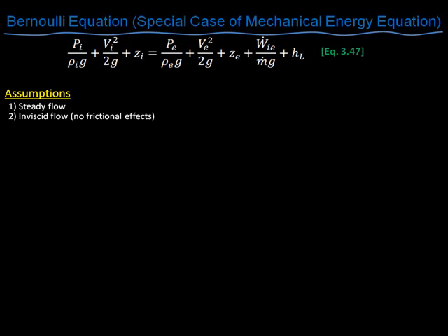We're going to assume that we're outside the boundary layer of the fluid, and so it's inviscid with air outside the boundary layer. There are other fluids that we could assume inviscid as well. And then adiabatic, which means there's no rate of heat transfer. So because of that, if you recall, when we defined head loss it was due to frictional effects, etc., and it was that thermodynamic energy that could not be converted to mechanical energy. If it's adiabatic and inviscid, that term goes to zero. Next, we assume that there's no power devices, so there's no rate of work. So the pump head or the compressor head or turbine head, depending on which term you're using it for, is zero.